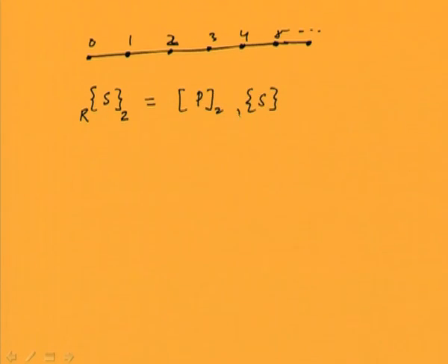So if we have a system like this in which various disks are here, these points represent the disks. So let us say 0, 1, 2, 3, 4, 5, all these are the disk locations. So we are able to write the previous equations, let us say I am writing here for this 2. So we develop state vector right of 2 is equal to point matrix 2 times state vector left of 2.